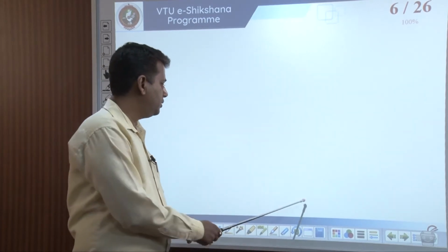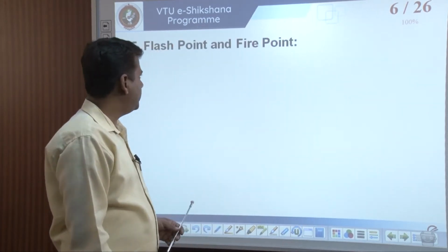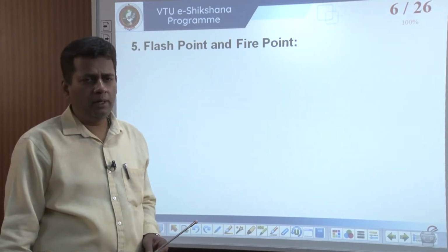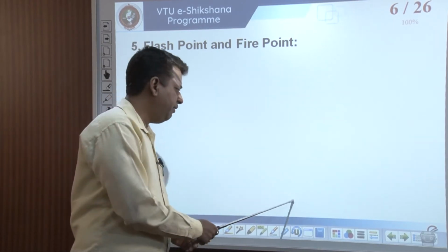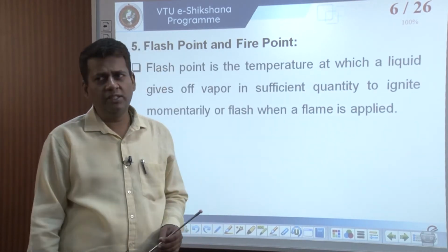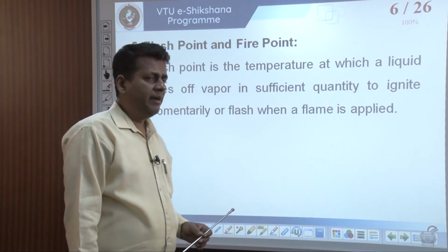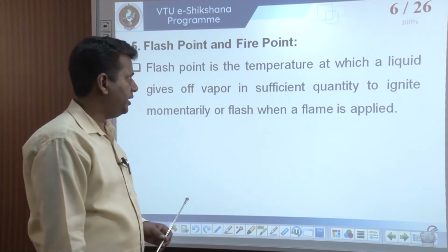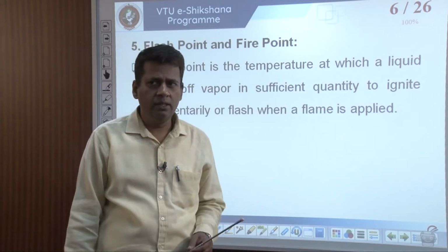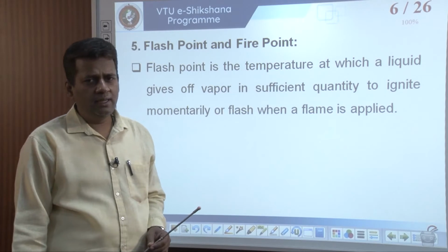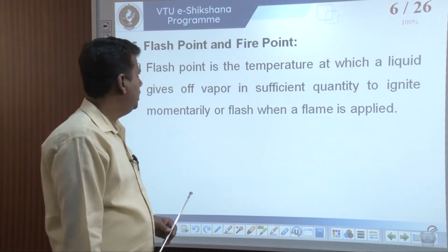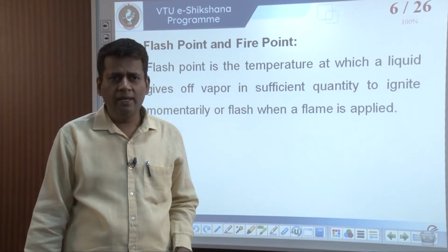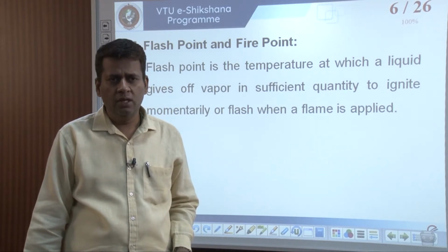The next properties are flash point and fire point. We know that these two points are very important. So, what are the flash point and fire point? The fire point is the temperature point at which the hydraulic fluid catches fire. The next is the temperature point at which the hydraulic fluid turns into a momentary flash. This is called the flash point.